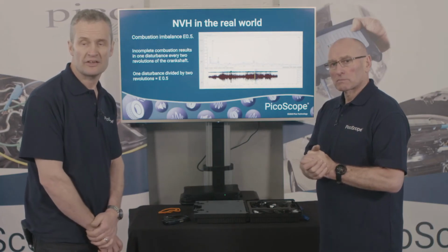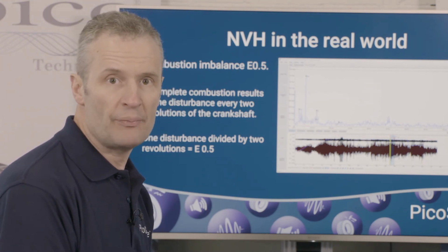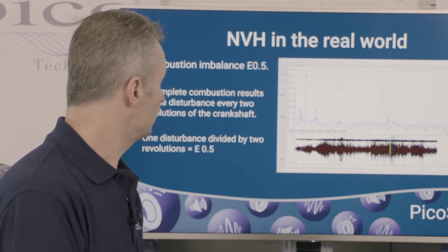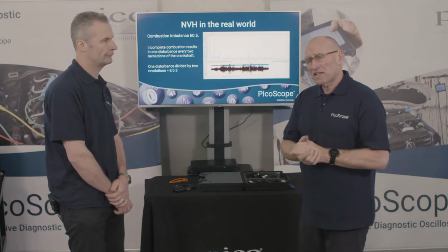Yes, it could also be components rotating at half engine speed, but think about when this occurs. This was during load, 3000 RPM, and clearly an unavoidable E.5 displayed in the spectrum. At the same time, we could feel the vibration in the cabin. I find this kind of data incredibly valuable because we often use the word misfire in inappropriate ways. Today we have a lot of issues relating to very serious engine damage because of incomplete or inefficient combustion. And combustion is, in effect, energy being imparted onto the piston crown, petrol or gasoline, and to be able to monitor this very simply from the driver's seat frame is absolutely an incredible first look, first choice tool when dealing with smooth running issues, as I say, petrol or diesel.